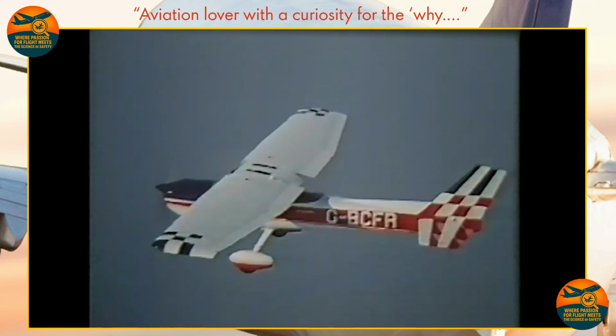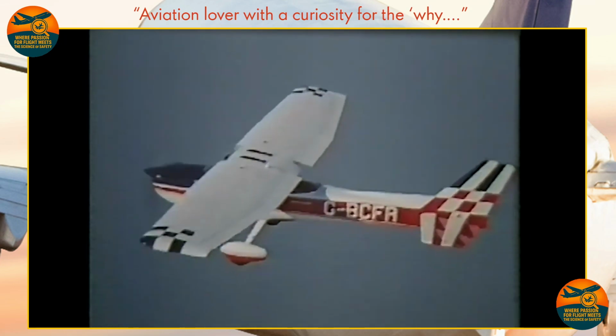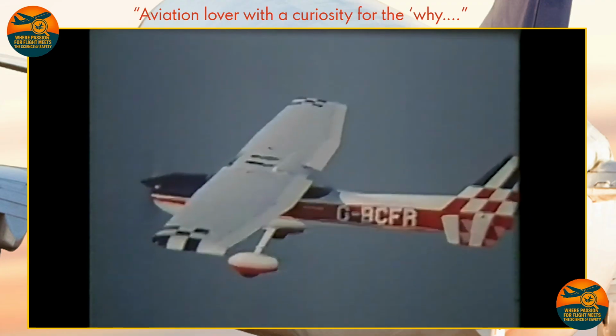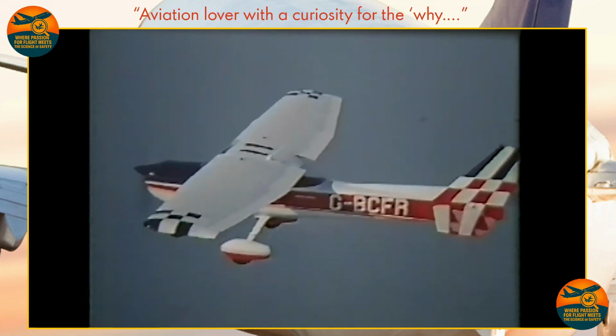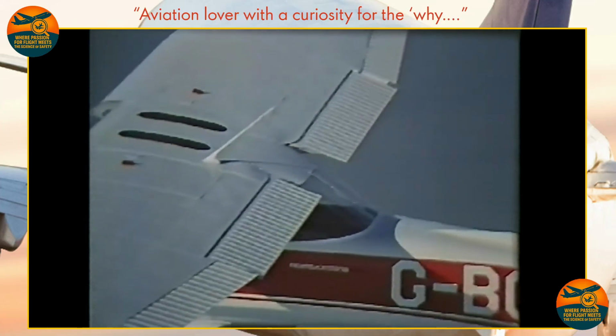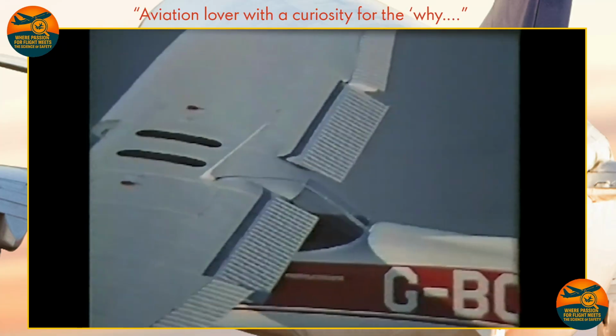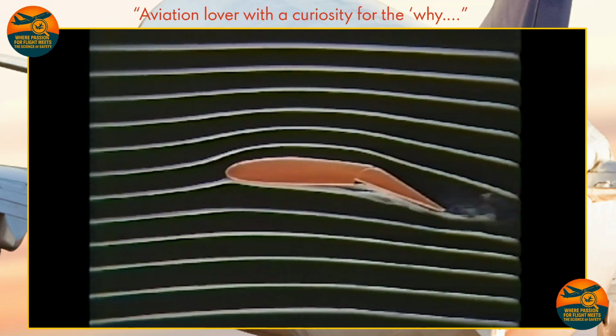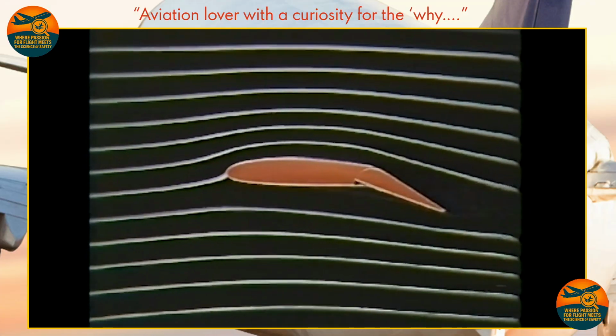Nevertheless, we must be able to fly slowly, and in particular to land slowly. To achieve this, we can change the characteristics of the wing by fitting trailing edge flaps. These flaps slide out from the wing and curve downwards as they do so. This increases the camber of the wing over part of its span.